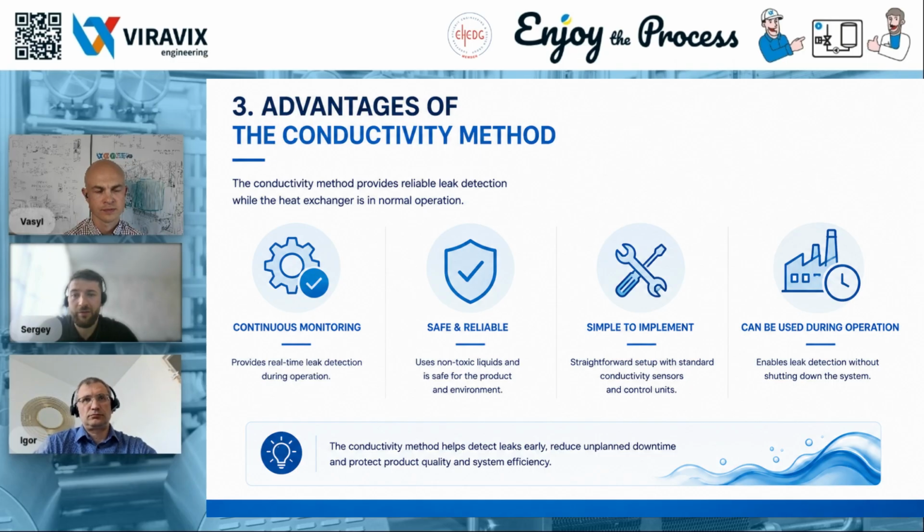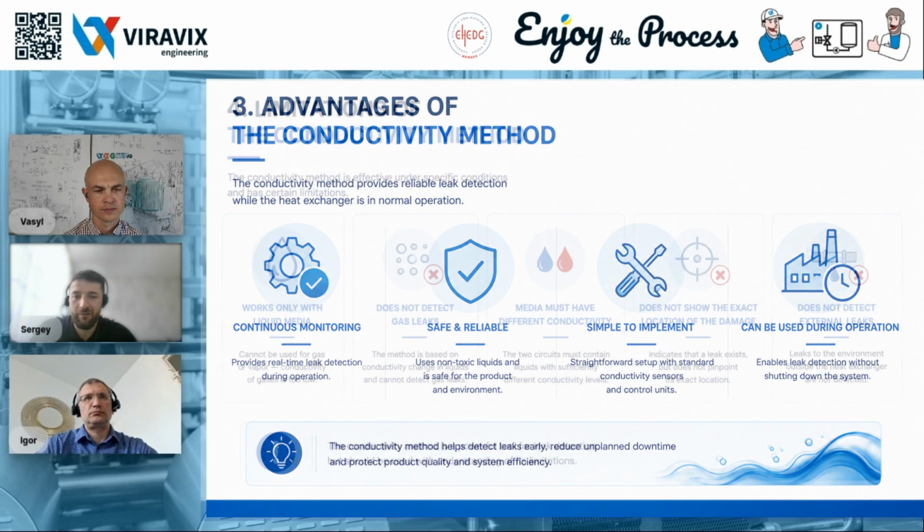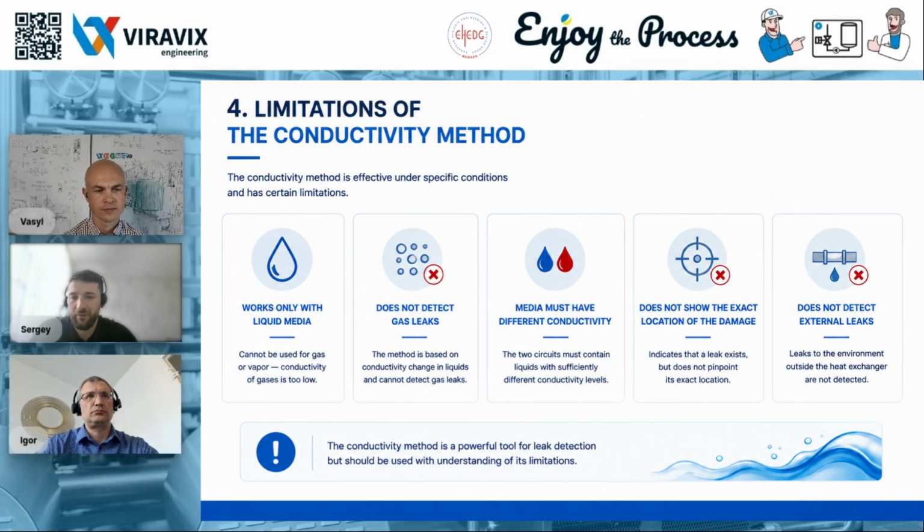As for the disadvantages, this method isn't suitable for every system. As we mentioned earlier, if the media in both circuits have the same electrical conductivity, the method simply won't work. It also can't detect gas leaks, as it only works with liquid media. Another limitation is that it doesn't show the exact location of the damage.